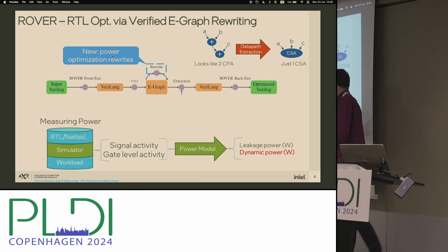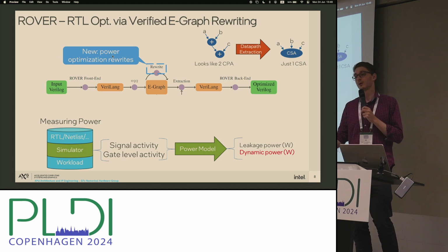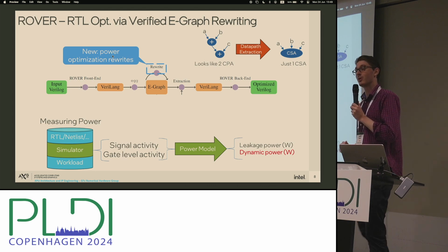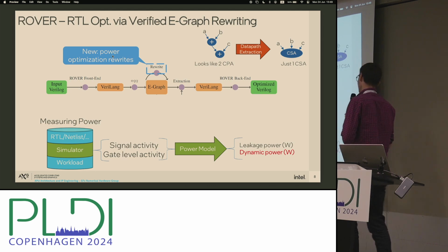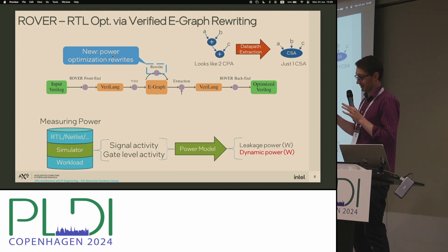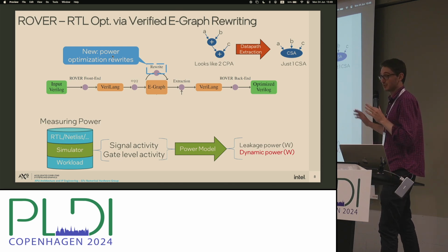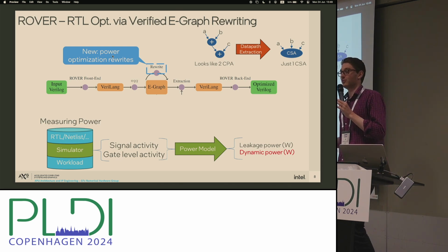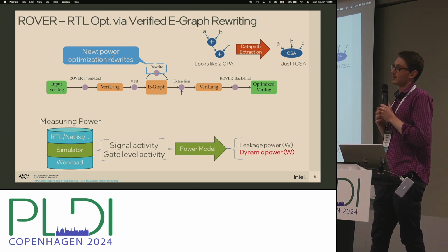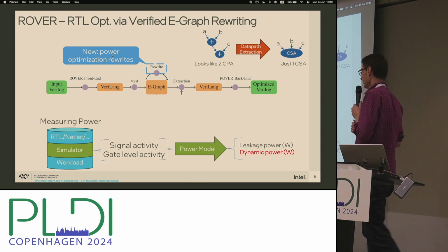And you have 2 notions of power coming out of this. You've got your dynamic power, that's to do with the transitions between zeros and ones that you intended to happen. And you've got this really nasty leakage power thing that we're not going to talk about because that's really hard to model, really difficult, but is also super important and is also a big consumer of how much your GPUs are actually consuming. And it varies massively depending on the particular hardware design.